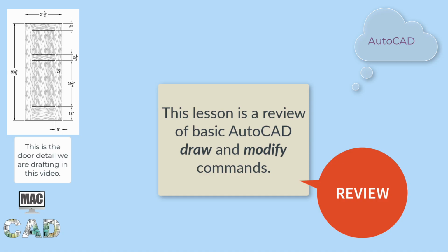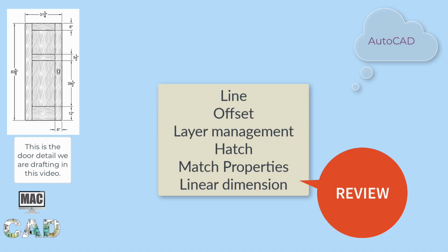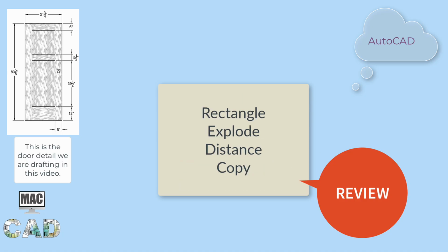The AutoCAD commands in this assignment include a review of the line command, offset, layer management, hatch, match properties, and linear dimension. Additional useful commands are rectangle, explode command, and the distance command for checking your work as you draft. Let's get started.